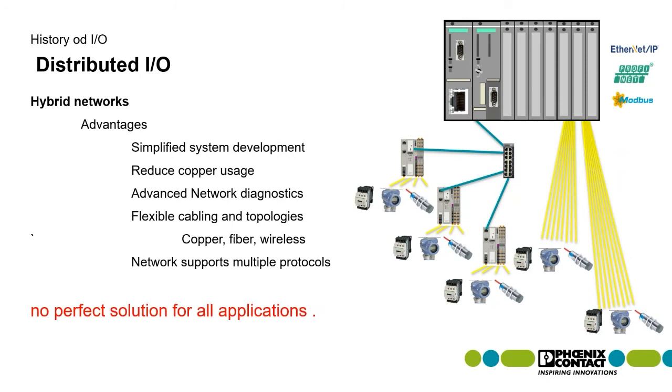But in the end, I would say all of the above. Actually, let me restate that. Not all of the above. In the end, I would say the first and the last is your ideal direction. You have machines, and there are always going to be IO points right next to the machine. Of course, just wire them directly to the IO cards for the PLC. Then as you get out of the cabinet and you break into your distances, that's where you start incorporating the distributed IO to collect those signals, and use Ethernet to bring that information back.